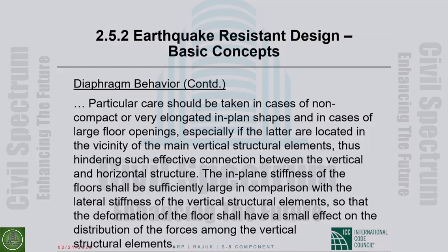The in-plane stiffness of the floors shall be sufficiently large in comparison with the lateral stiffness of the vertical structural elements, so that the deformation of the floor shall have a small effect on the distribution of the forces among the vertical structural elements.